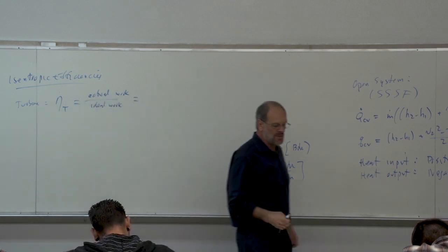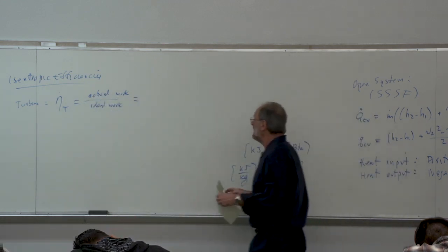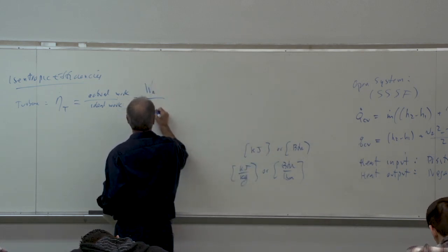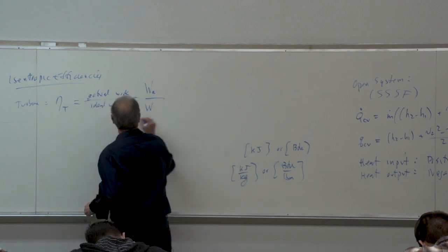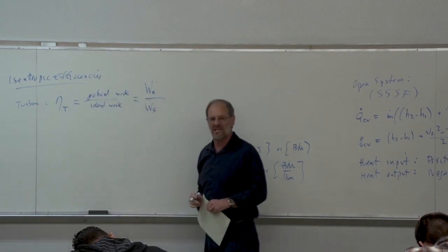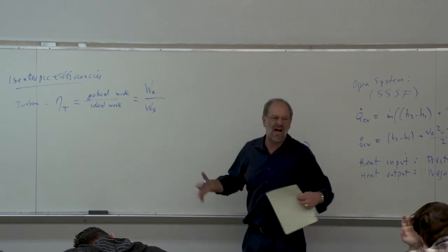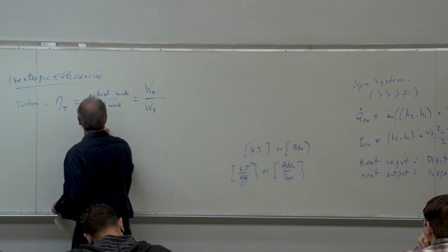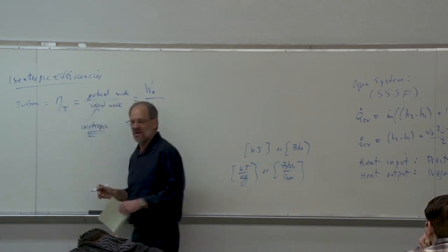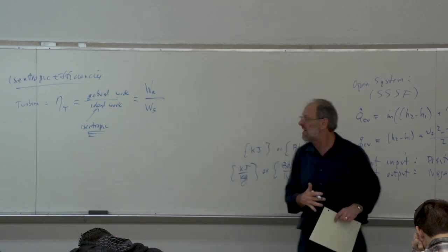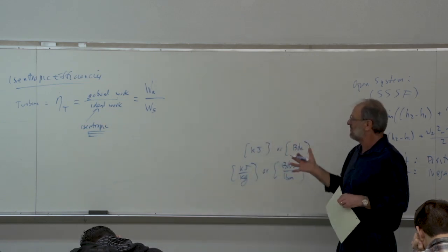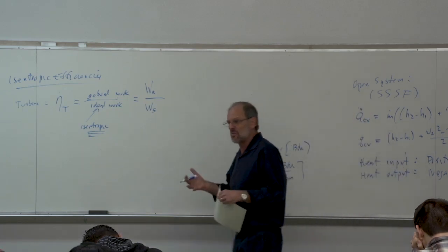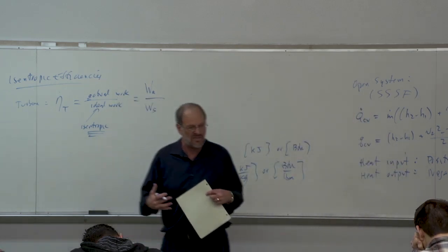So what we're going to do is use a couple of subscripts. A represents actual, and S represents ideal. Now, why S? Why don't I have an I or something like that? Keep in mind that when we talk about ideal work, we're talking about an isentropic process. Adiabatic reversible, that's isentropic, and an ideal turbine would be one that is indeed isentropic. That can't be achieved. In the real world, there are always losses, but it does represent a theoretical limit.